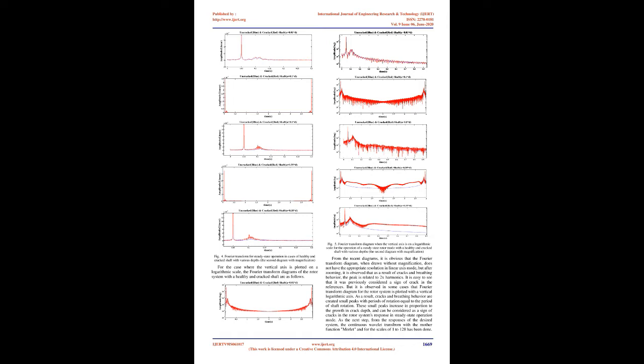By inverting the flexibility matrix, and using the transfer matrix T and its transpose, the stiffness matrix of each element of the shaft can be obtained. The total stiffness matrix of the shaft can be extracted by adding all the assembled element matrices together. It should be noticed that the procedures described in the previous section are used to assemble the stiffness matrix. In this way, the stiffness matrix of all elements except the element containing the crack is equal and remains unchanged.